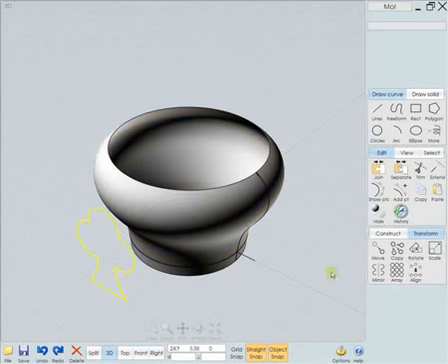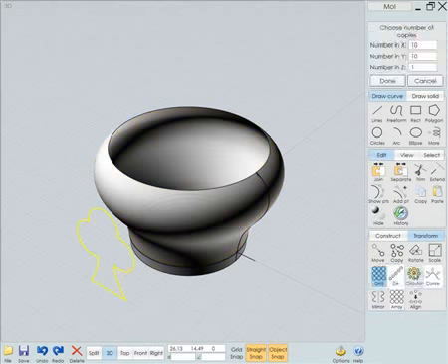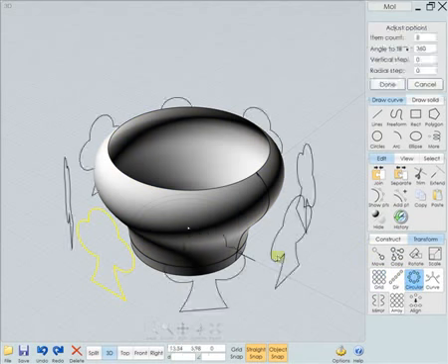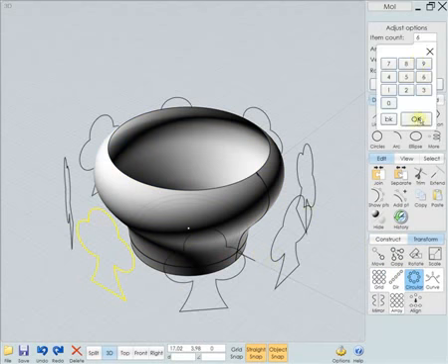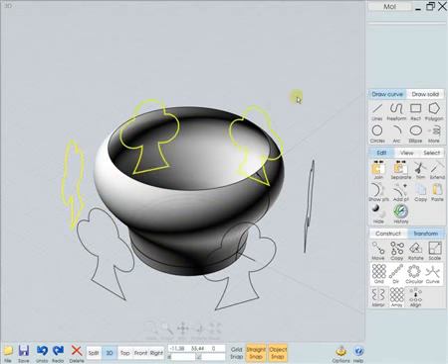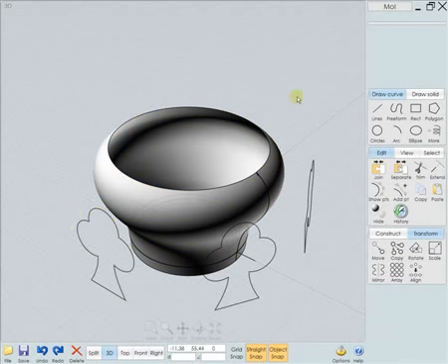Now let's take this and say array circular, snap onto that origin point again, and let's give it 6 copies around. And let's delete these 3. Now we would like to cut this shape using these. Now a Boolean difference that cuts holes in things would leave club-shaped holes in the shape, but we don't want that. We want to cut away everything else and only keep the areas of the clubs, and that's what the Boolean intersection tool will do.